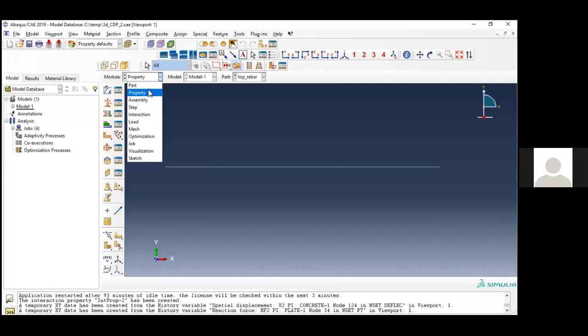And second thing, sir, if you want moment of inertia, bending moment at one particular section, does it calculate with respect to steel also, or only when it is elastic? Suppose I want the bending moment at half the length of this particular span. Can I get that value? Because we need moment to get steel design. In SAP and ETABS, we will get moment at every point. Similarly, can we get it in ABAQUS? No, because this is a 3-dimensional stress analysis, right? You won't get moment directly.